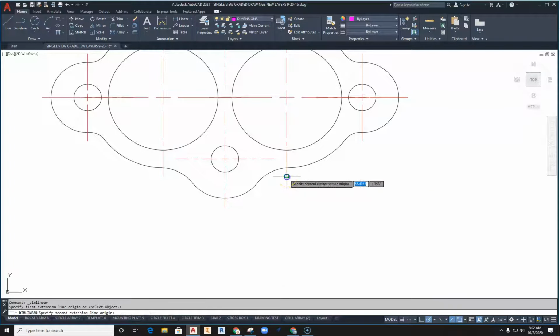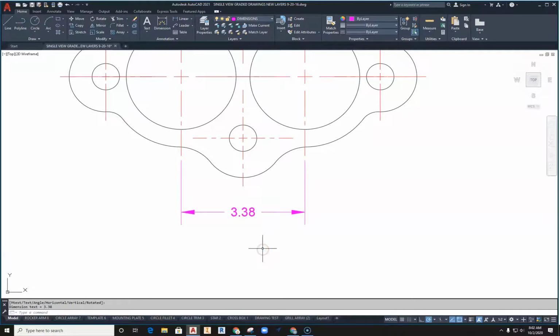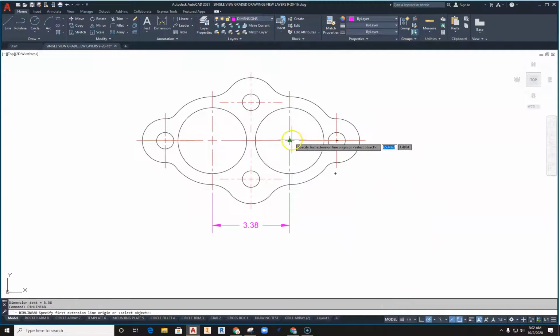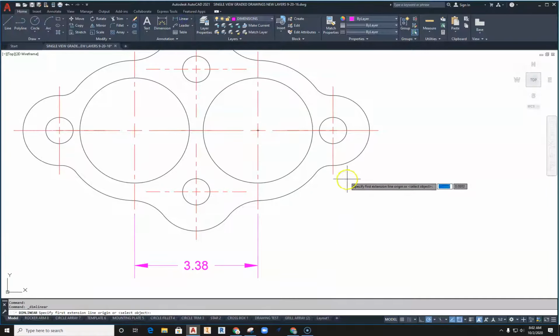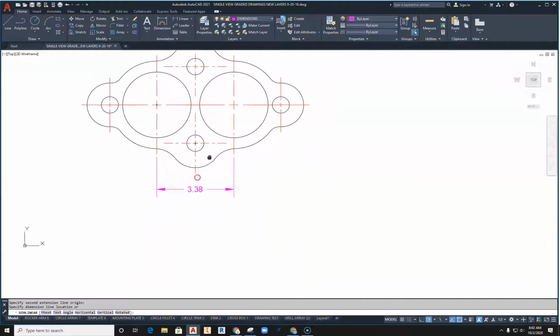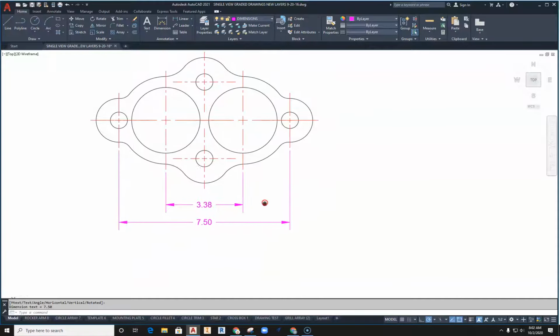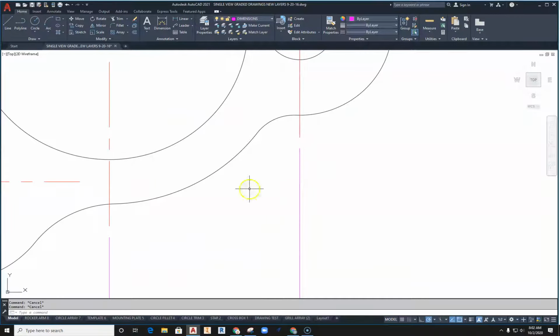And then when you select the end of the center mark and end of the center mark, pull down and drop the dimension. Okay? When you start dimensioning circles, don't go from the center of the circle to the center of the circle and pull down. That is a sloppy way to dimension because you're running over top of your center mark. Okay? What you want to do is grab the linear tool. You want to go from the center mark to a center mark, pull down, and then drop the dimension. Okay? You want to have a gap right here.